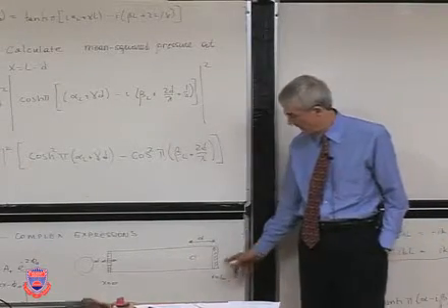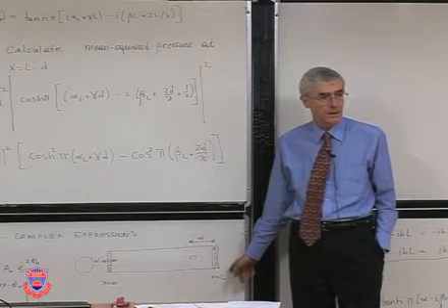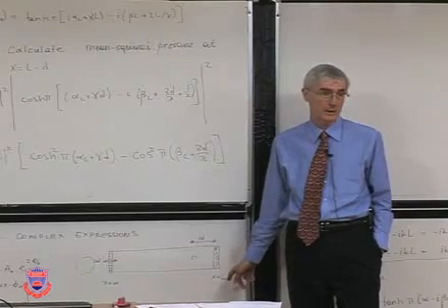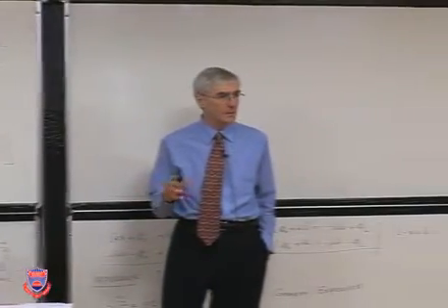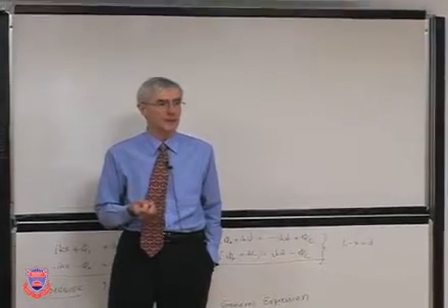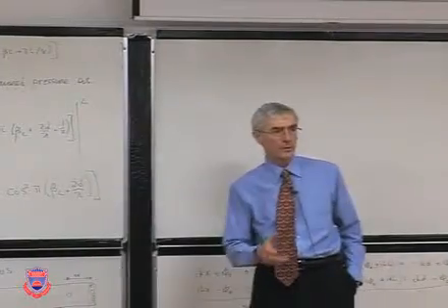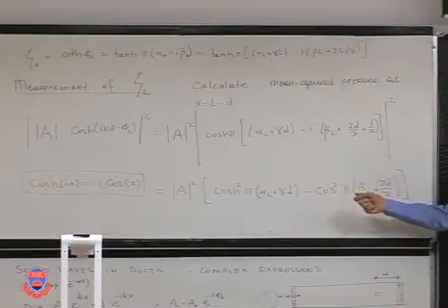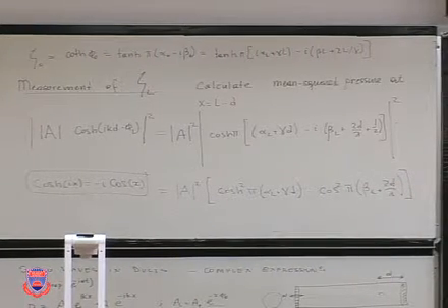That means now we have a general expression where the impedance at the end, or the boundary condition at the end, is neither perfectly rigid nor perfectly pressure release. It's somewhere in between, and that's called an impedance boundary. After a few minutes break, we'll come back and see what this means, and using this, how you can obtain an impedance value by sound pressure measurements.